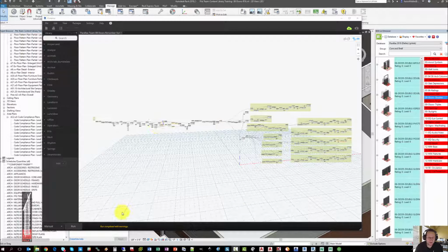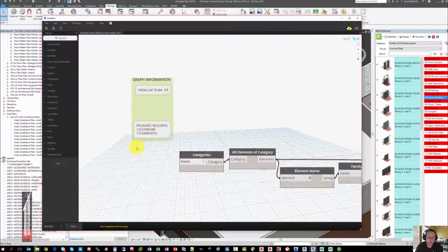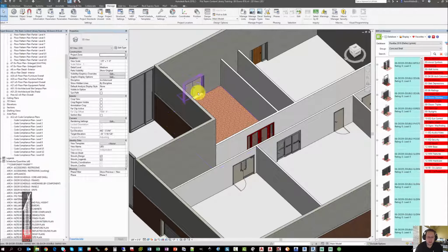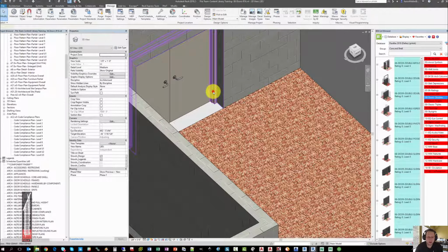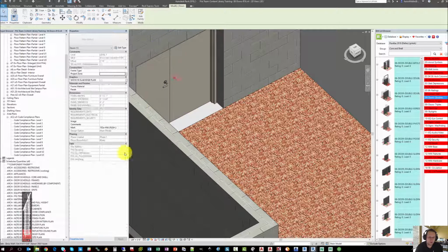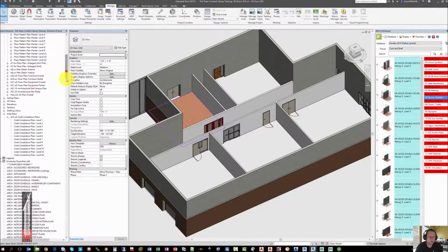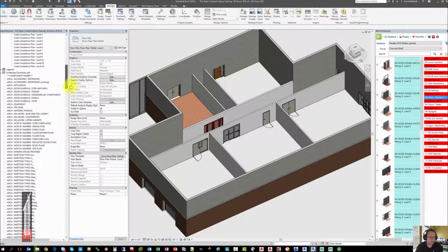When it's completed, it may either say run completed or run completed with warnings. That's going to depend on a couple of things in your project. By the way, keep in mind that this graph will require you to download a couple of third-party packages before it will run. What it's done is it's now gone through and numbered all of your subcomponents: 102A frame, 102A hardware push panel 2, 102A hardware push.